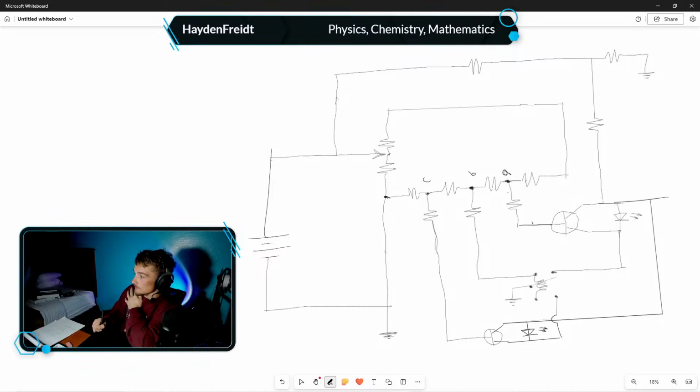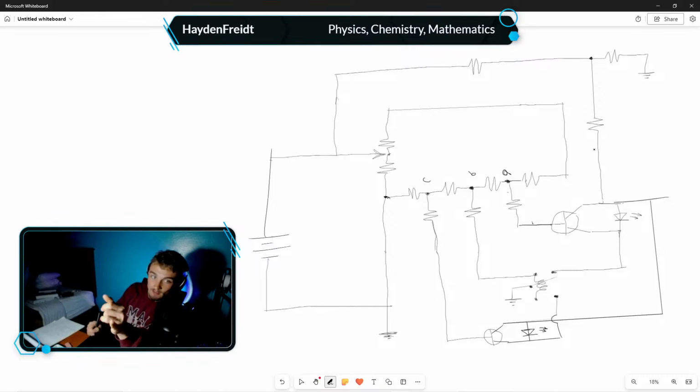Okay, so this will be the first transistor to activate, which will obviously activate this LED, or allow the supply from right here to even get to the LED, which also requires a current of 20 milliamps for green LEDs, and I think it increases with the color of the LED. It depends, but 20 milliamps is what we're going to be working with.